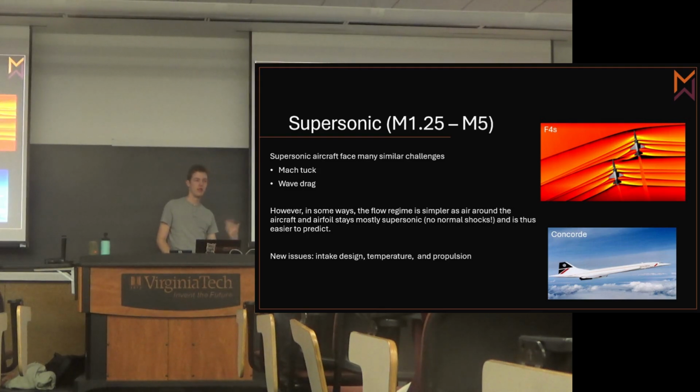Transonic is where you have to deal with both supersonic and subsonic airflow, although usually these aircraft also have to operate in both regimes anyways. But I always find it funny, you read about the X-1 or whatever, they're trying to break the speed of sound, and the aircraft is shaking and shaking and shaking as they're getting through the transonic region, and then right when they go past Mach 1 and into fully supersonic, it just smooths out and the aircraft stops shaking. Because it doesn't have to deal with both of these types of airflow at the same time, and things seem to behave better. But don't worry, there are new problems from going faster.